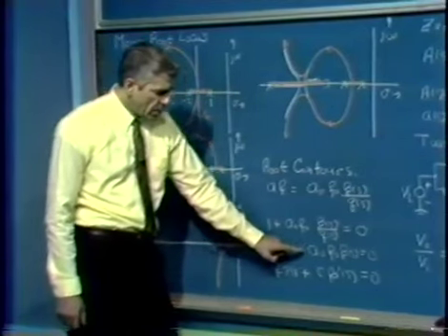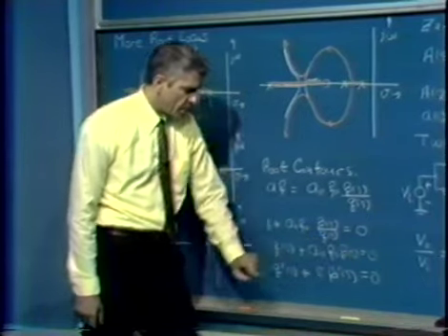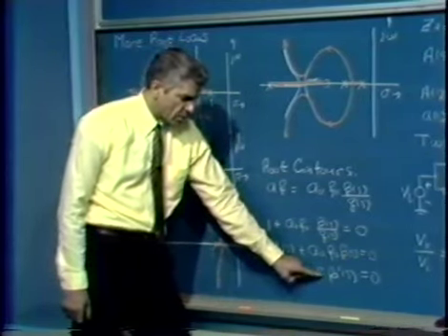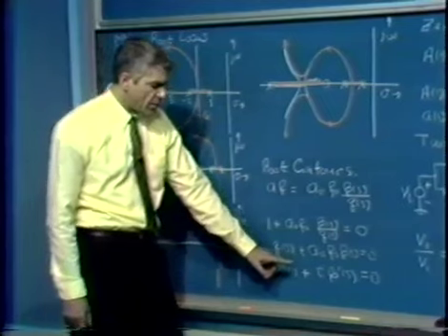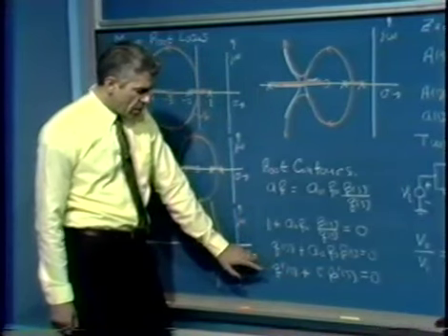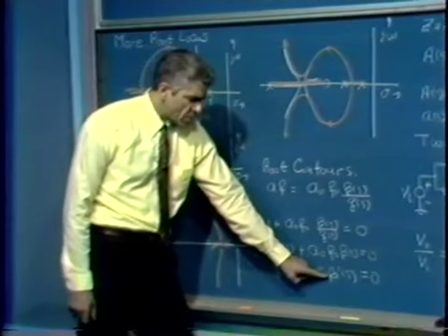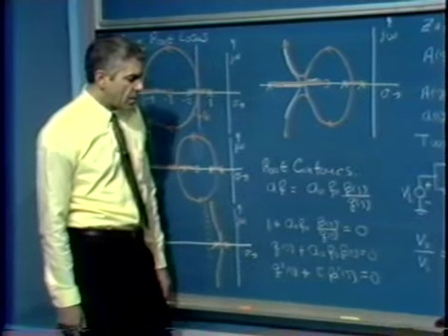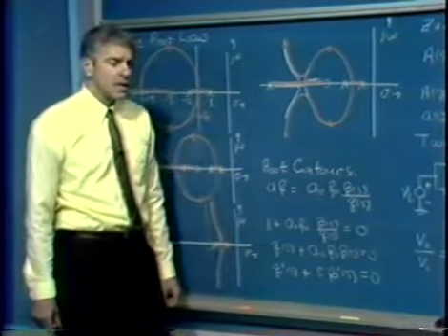Here we have a polynomial plus the variable that's going to change as we construct the root locus diagram times another polynomial being equal to 0. So once we've made this identification, factored out the variable parameter tau, we can consider a system which has zeros that are determined by q prime of s, poles that are determined by p prime of s, and we can use exactly the same techniques for construction now of a root contour diagram as we did for the construction of our root locus diagram.